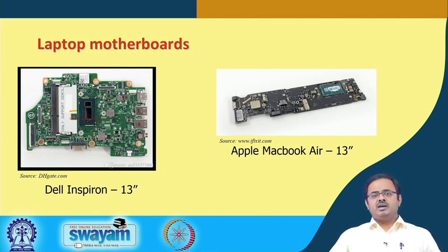So, these computers sometimes have motherboards that are 4 layer, a lesser number of layers, because you do not have so much functionality, so many interconnection points and so on. The processors are not that powerful, not that many interconnects. So, in such cases you can go with a lesser number of layers in the circuit board. If you look at tablets, smartphones these days, they will primarily not have too many layers inside them, definitely not 6 or 8.